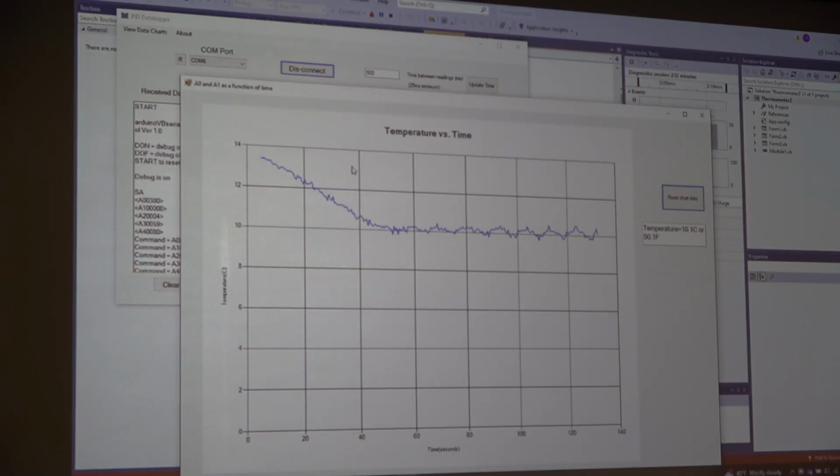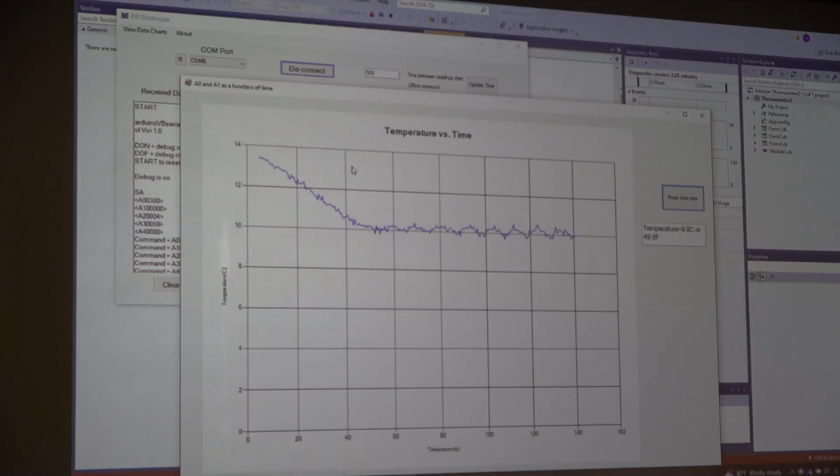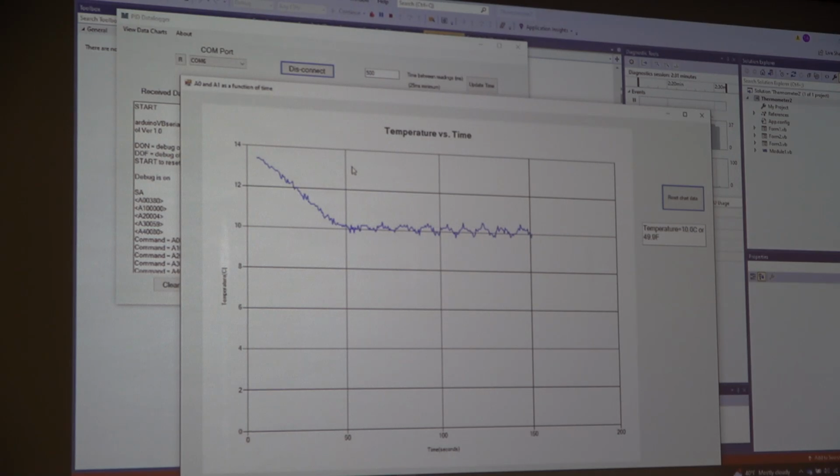So when I got P and I, I showed you that I've got this situation where I'm driving my boat, and if I've got too much I on, I'm bringing that throttle up over time because I'm getting bored, which means my error can go to 0, and I can hit the set point with way too much speed. That's where D comes in.